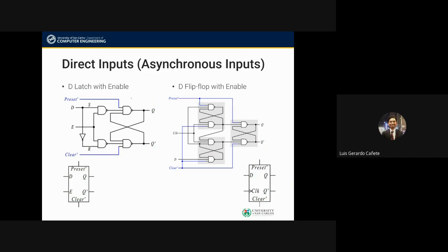It depends on which one of these two goes to 0 first, right? So when this would go to 0 first, it would automatically say that this is 1, so that this would then become 0. Okay? It maintains that. So to ensure that when your system starts up, all the outputs of the latches are either all 1 or all equal to 0, we use asynchronous inputs.